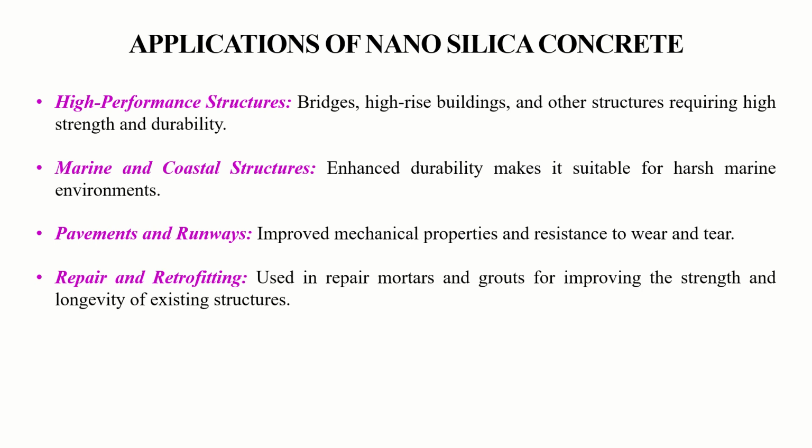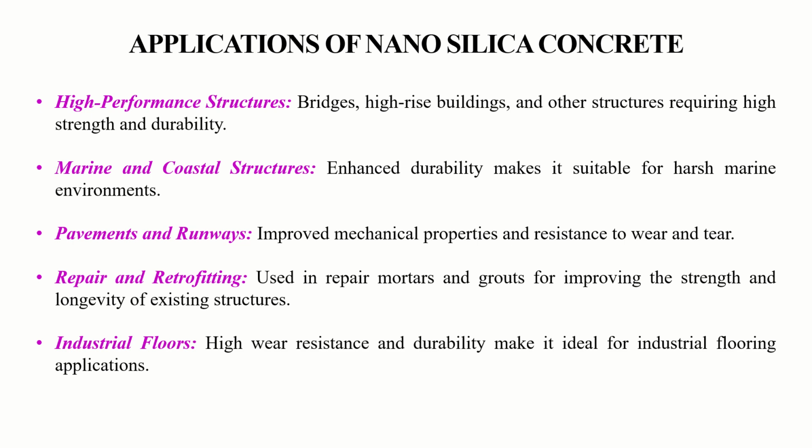And nanosilica concrete can also be adopted for repair and retrofitting of structures, like grouting, mortar, or as a filling material for cracks, etc. And industrial floors, because it is resistant to chemical attacks and has better durability, so it can also be used for industrial flooring applications. So that is about nanosilica concrete.